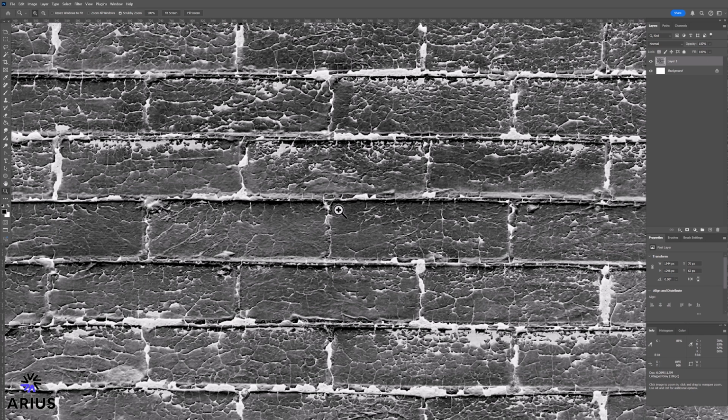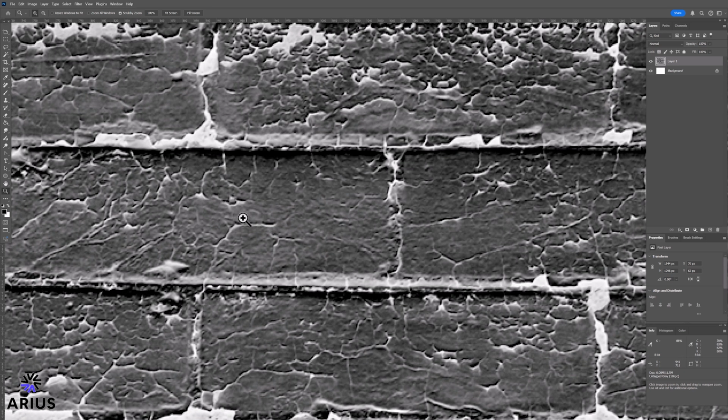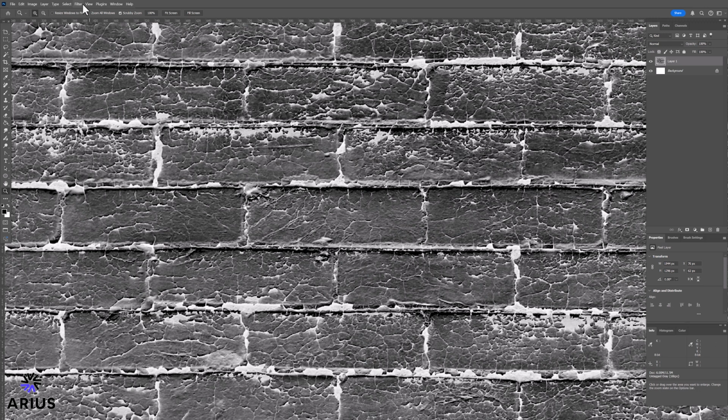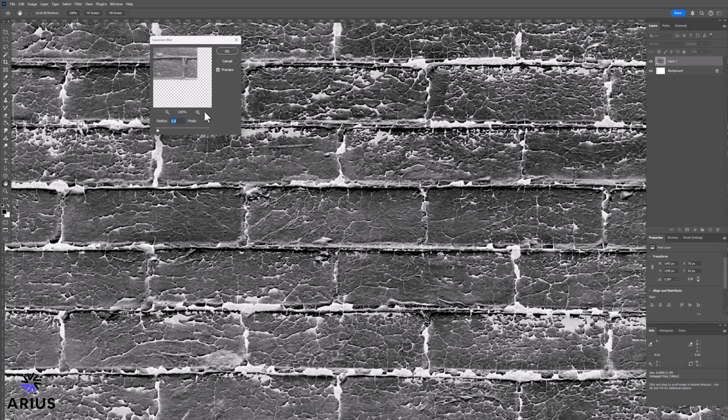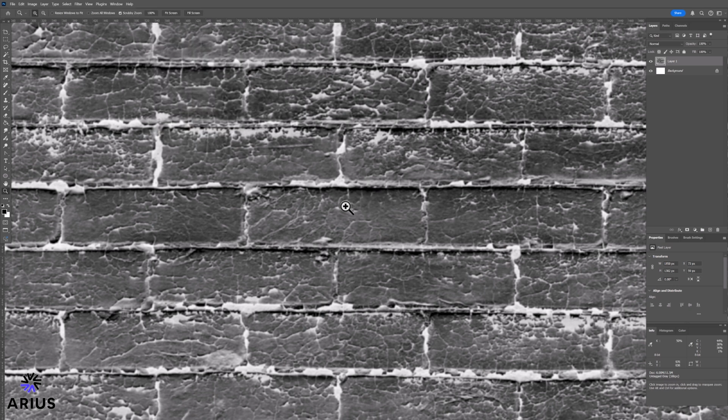The current sharpness of the image, when converted to a point cloud preview, shows many areas of high contrast in the details, and therefore noise or walls in the final print. A best practice is to do a small Gaussian blur at 1 pixel to remove their hard edges and rely on just a color image to render those fine details. This will reduce the chances of unwanted anomalies overall.